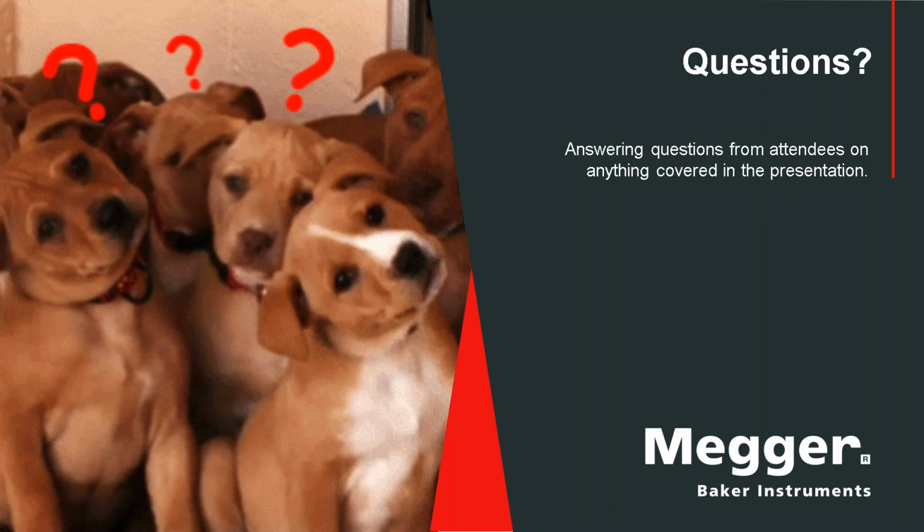Static testing is going to tell me where my insulation is, and dynamic testing is going to tell me those conditions that are going to degrade my insulation. So while dynamic or online testing won't tell me about the insulation, it'll tell me about those things that are degrading my insulation.